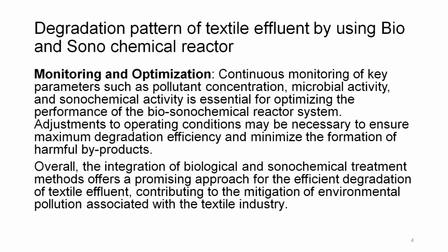Monitoring and optimization. Continuous monitoring of key parameters such as pollutant concentration, microbial activity and sonochemical activity is essential for optimizing the performance of the biosonochemical reactor system. Adjustment to operating conditions may be necessary to ensure maximum degradation efficiency and minimize the formation of harmful byproducts. So, unless we are assured that the bioreactor part is working efficiently, the microbial activity is happening properly, and whether the sonochemical activity is happening properly or not, we will not be able to decide whether the reaction is going on as per the desired mode. So, monitoring and optimization becomes very important.